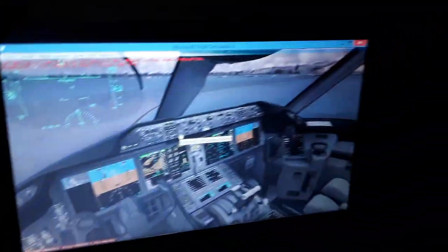Also we have the nose wheel steering, the tiller, the forward nose wheel steering on the ground from 0 to 70 knots is active, decreasing deflection left and right, down to like 7 degrees at 40 knots in takeoff, then it decreases from 40 knots to 70 knots, from 7 degrees to like 0. So you have only the rudder after for takeoff for directional control. So the rudder is aerodynamically effective at around 45 knots airspeed in takeoff.